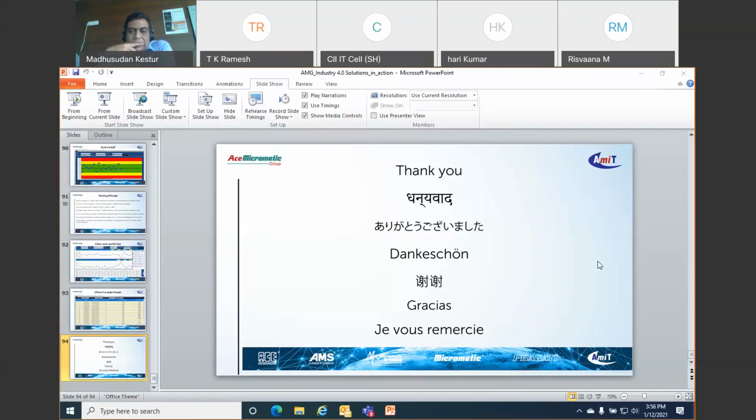To measure the cycle time, we integrate a piece of hardware, or we leverage the controller APIs to look at the cycle times from the machine. The gap between one part ending and the next part starting is called the load unload time, during which the finished part is unloaded and the next part is loaded. We take all these times and then arrive at the performance efficiency of the machine or the process.